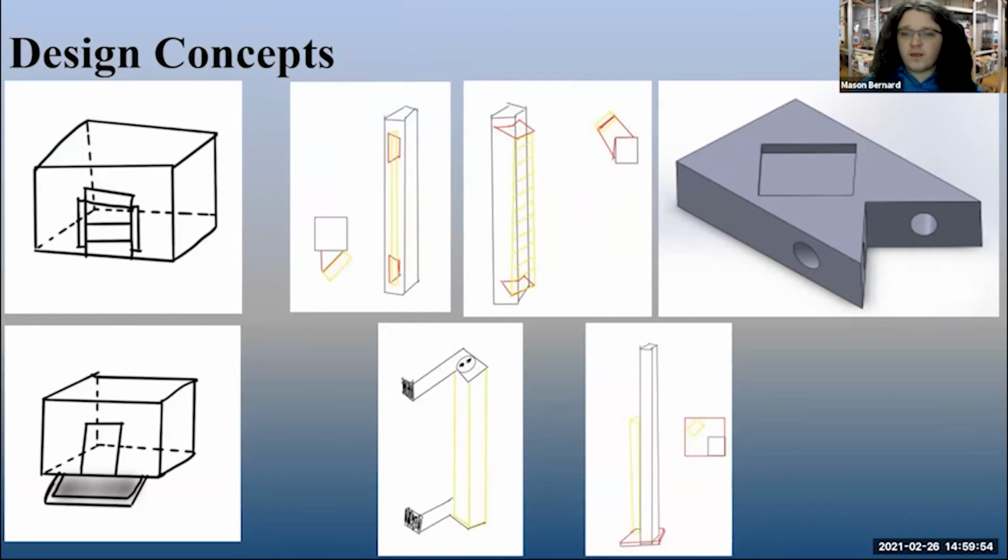This first photo is a multi-beam system that has very limited beams in comparison to the light curtains. So you could easily stick your arm in and not be detected, and a robot could just come up and chop it off. It's very ineffective. Below that are the safety mats. They are pretty good, but they lose durability, and along with that, their reliability just plummets. So we're not going to be using those.